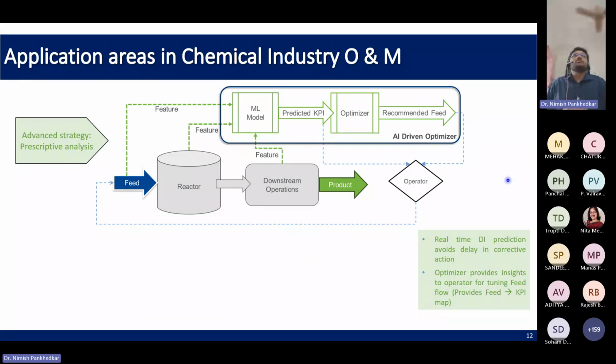Right. Since you took an example of a distillation column, what is mostly developed as soft sensors are the composition analyzers. In my initial example of the DMA distillation, or let me take an example of an ethanol water distillation column, it is crucial for me to know what is the top purity at every point of time. So you might have to correlate the temperature profiles, and the upstream compositions if you have the analyzers for them.